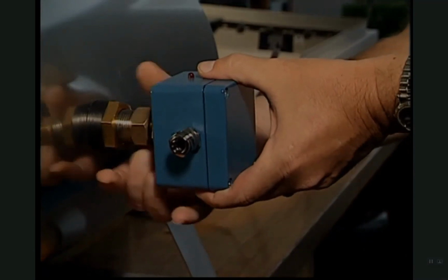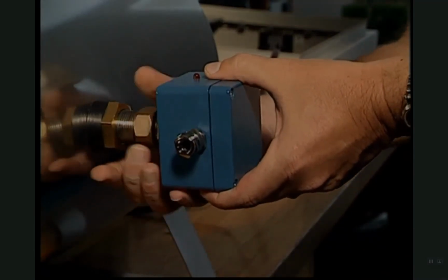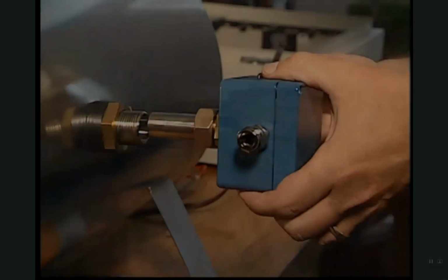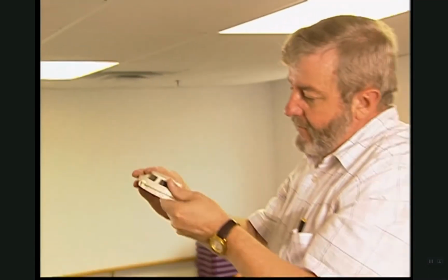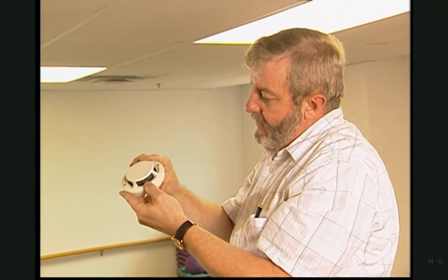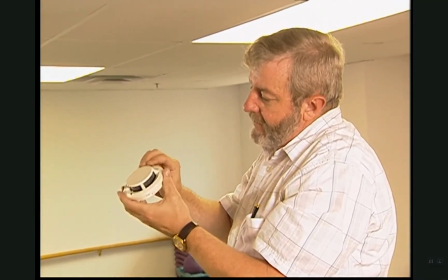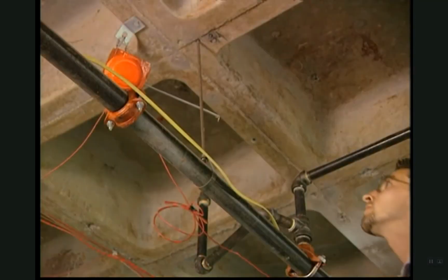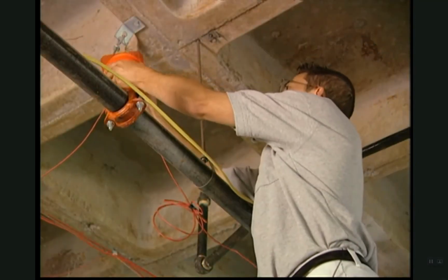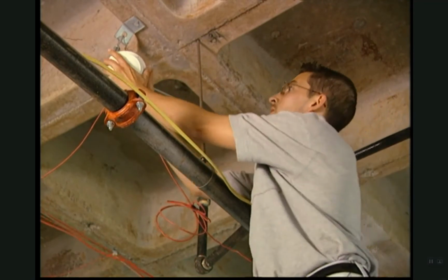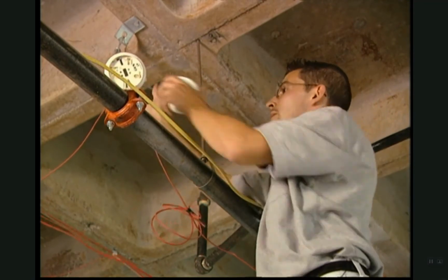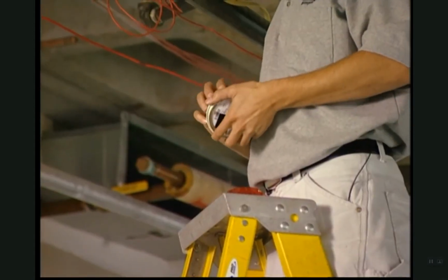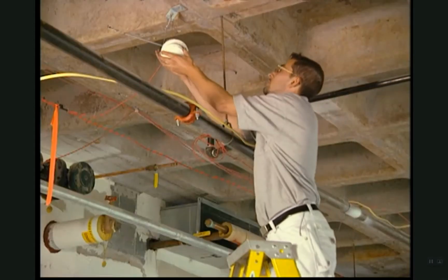Radiant energy fire detectors should also be inspected quarterly. Make sure the lenses are clean and free of contaminants. All other initiating devices should be inspected semi-annually. Make sure heat detectors haven't been painted over or rendered ineffective by new construction. Check smoke detectors for blockage or contamination. Make sure nobody has left in place what was supposed to be a temporary cover to prevent contamination, for example,